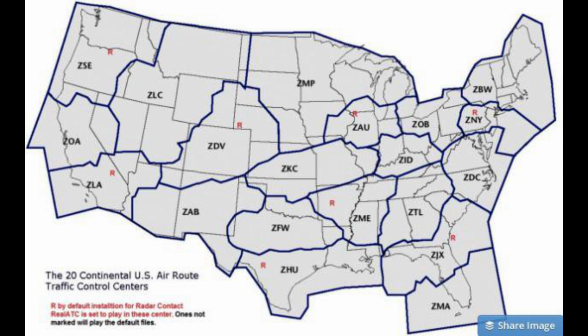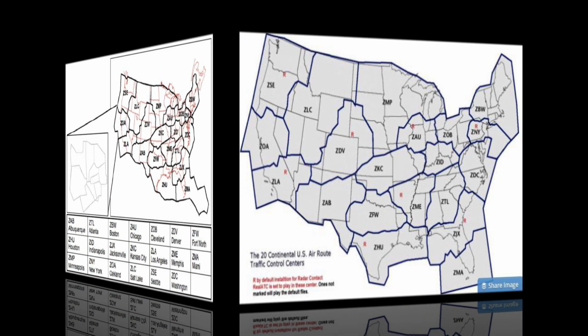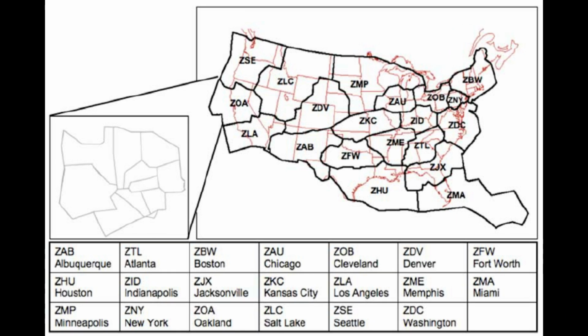To develop a flight plan, select pitch and catch points, which can be found in the Chart Supplement (CS), based upon your desired route across the Phase 1 airspace. Filing requirements to pitch points and from catch points remain unchanged from current procedures. For the portion of the route between the pitch and catch points, NRR is permitted.